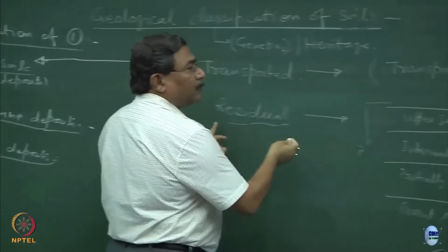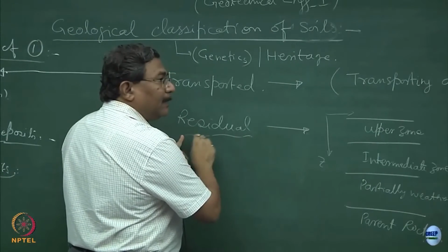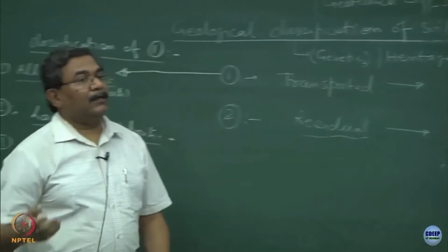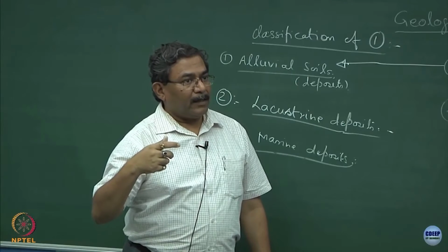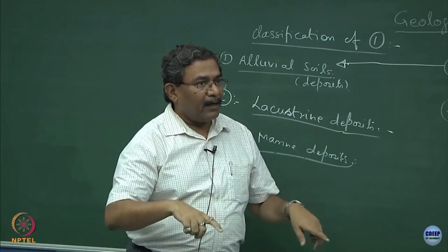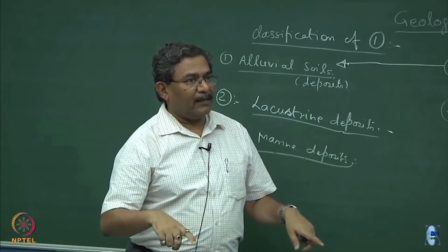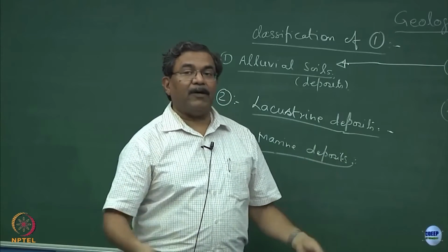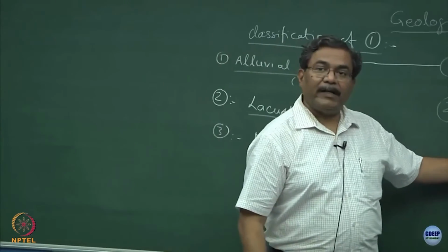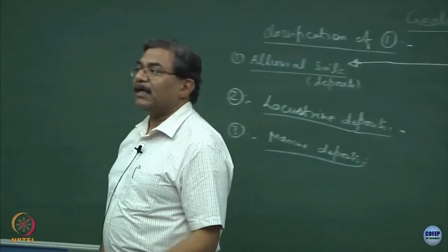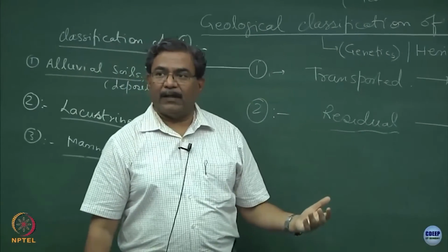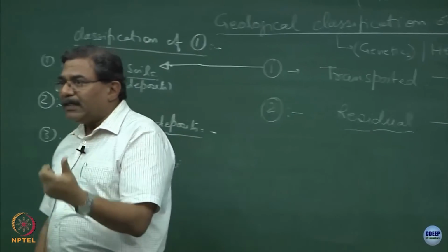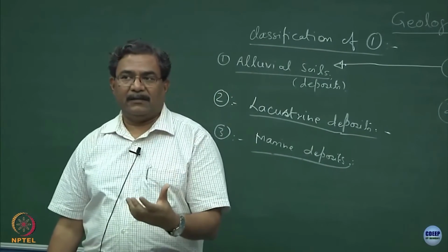Those of you who will be taking a course in offshore engineering will realize this very soon, that these residual soils are the ones which got created because of the weathering of the granite or basalt, clear, and they remain there. They had a lot of organic matter in them, they got disintegrated because of bacterial activity and they got converted into clays. Clays is another variety of soils, what you were referring to, mud or slush. Slush and mud are not technical words, clear. So, we have introduced two words today, one is sands, another one clays, fine.